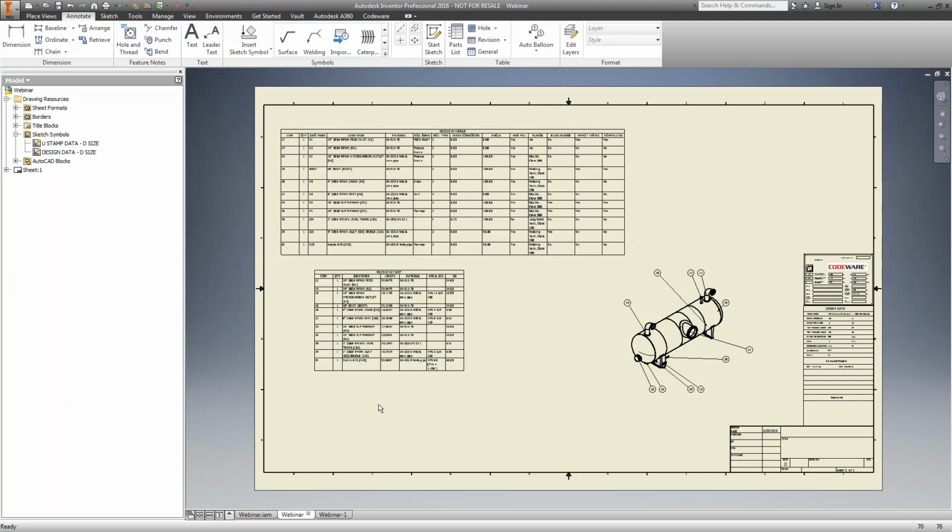In the event that the drafters have to move something, let's take a vertical tower, for example, and you have to move the nozzle elevation, I would highly recommend you check with the engineer designer and go back to Compress, because that could fundamentally change the code calculations as well. So currently it's a one-directional link. But what you can do is make the change in Compress and very easily re-export the model as well, and it should get updated for you.